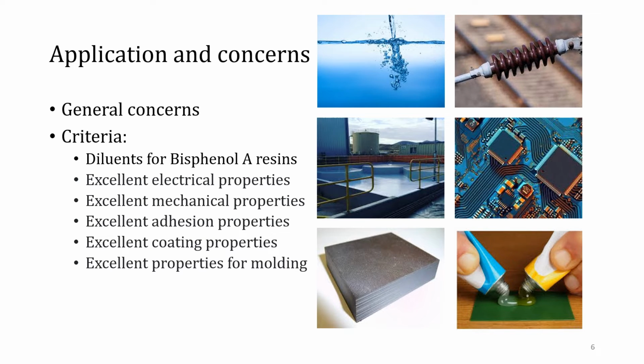Cycloaliphatic epoxy systems generally cost about 25% more than ordinary epoxies. In many applications, they are not necessary, but they certainly are for clear tabletops and bar tops. Cycloaliphatic epoxies are good for things like tabletops and bar tops and are also used in modern telephone pole wire insulations. Moreover, cycloaliphatic epoxy resins are used in applications where improved outdoor resistance as compared to standard bisphenol A or bisphenol F diglycidyl ether epoxies is required.